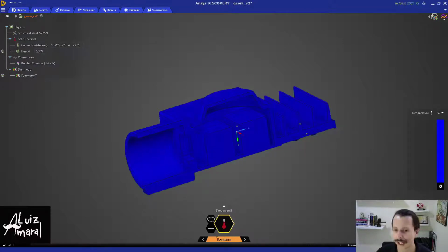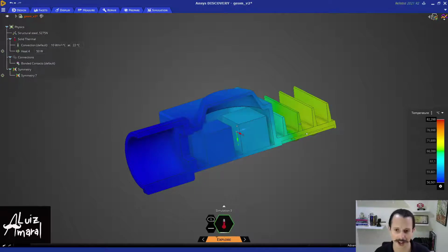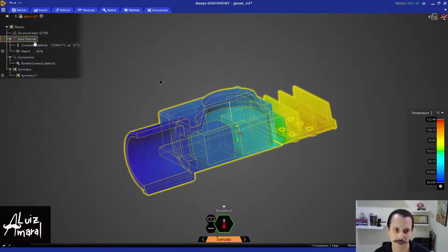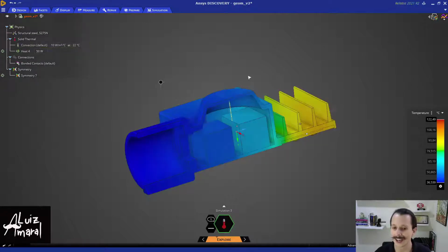We can start playing around, just as simple as that, and take into consideration some details for us to understand how our product works. So in a matter of 2 clicks, 2 definitions of my device, all other boundary conditions were defined as convection surfaces, and already we can see results like maximum temperature, minimum temperature, and why not? We can create our own.